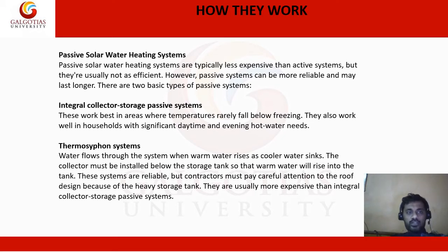In thermosiphon systems, water will flow through the system when warm water rises as cooler water sinks. The collector must be installed below the storage tank so that warm water will rise into the tank.